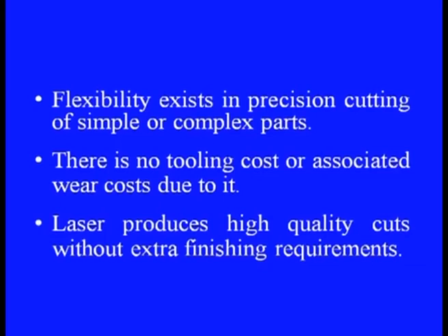Holes can be located accurately by using an optical laser system for alignment. Flexibility exists in precision cutting of simple or complex parts. There is no tooling cost or associated wear cost, since there is no physical contact between the tool and the workpiece.